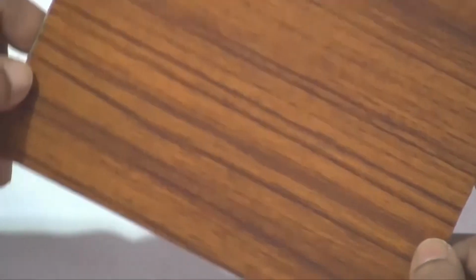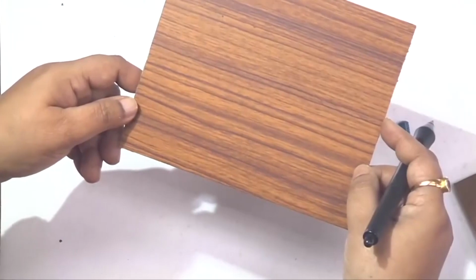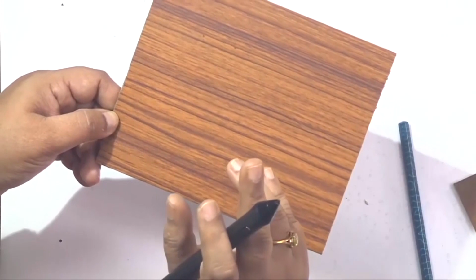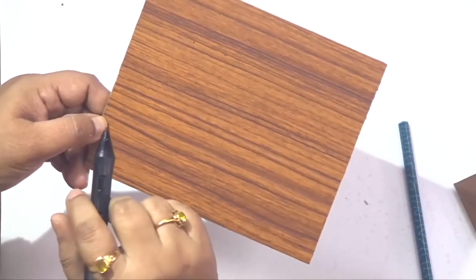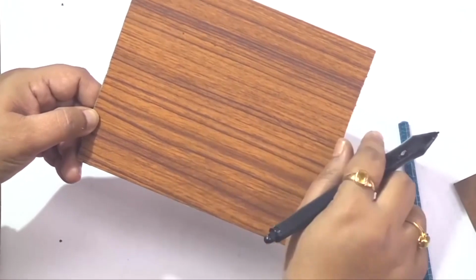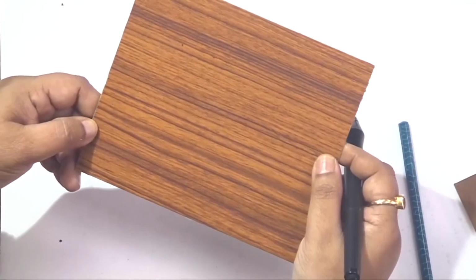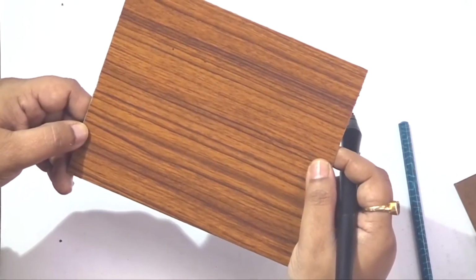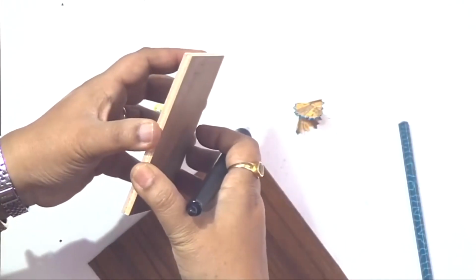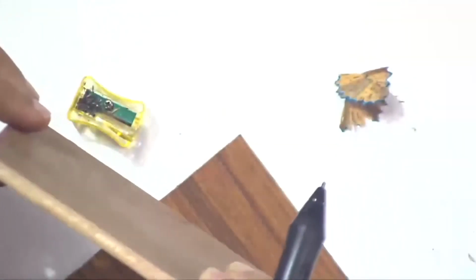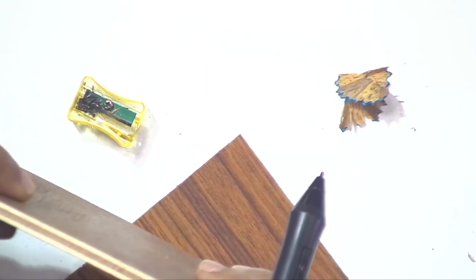You can have a finish similar to that of good quality wood, and no one can understand what is inside it unless it is moistened and the adhesives get loose. So, that has to be remembered, that the adhesive should be proper, it should not absorb moisture. Once it absorbs moisture, these plies, these veneers will just come off. So, that will lead to the decay of the item.